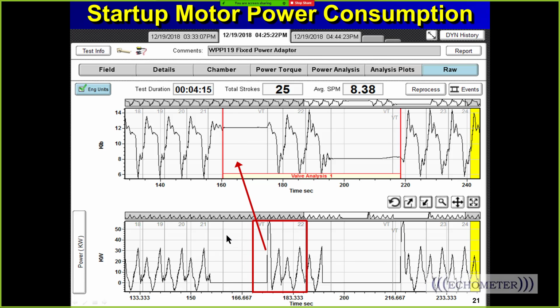So why am I telling you all this? Well, if you have a pump off controller or percentage timer, and you turn on the well every 15 minutes and off every 15 minutes, then you're starting and stopping about 96 times a day. And if you save 1 stroke, that's equal to the power used to run the well during 1 stroke to start it up, and you save power by not running your unit all the time if your pump's not full.